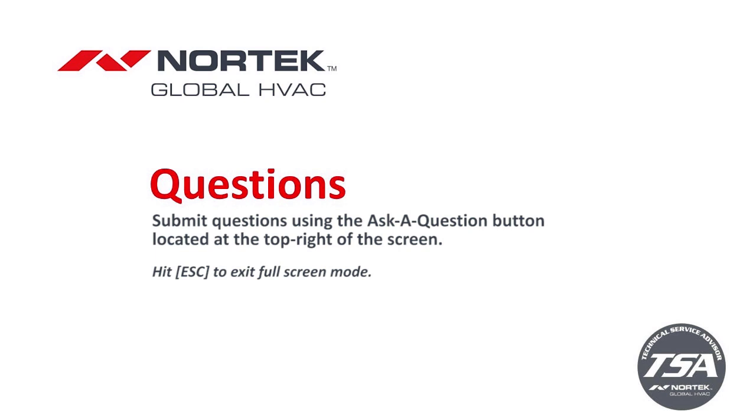Okay, so Mr. Michael's got a question here. His question is in regards to setting dip switches on the 90+% furnaces and the 80% furnaces that would have to be set. So per your question, and this also applies to the air handler side, when you do have an ECM motor on the indoor, you do have to set the dip switches. Now, this rule would apply to both the 80 and the 90.